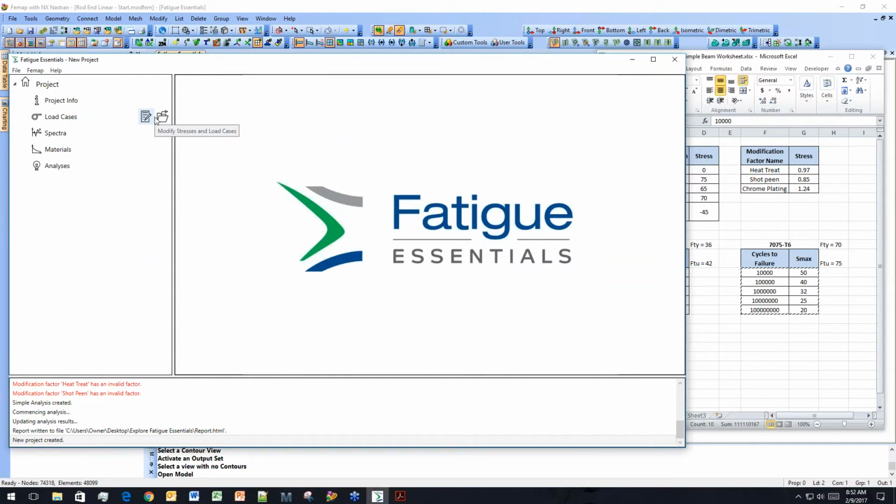Now, running Fatigue Essentials in conjunction with FEMAP is fairly similar to the classical method that we just looked at. You're still going to need a spectrum. You're still going to need materials. The difference is your load cases get pulled in from FEMAP, and the analysis, we have an option to push the damage plot back out to FEMAP.